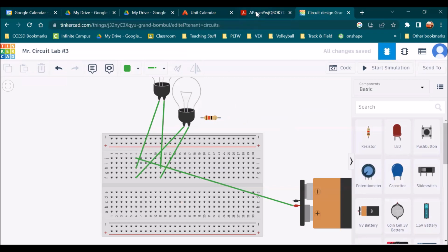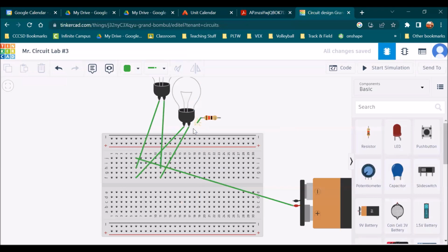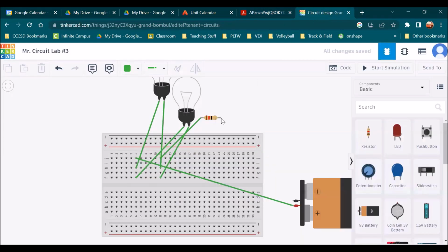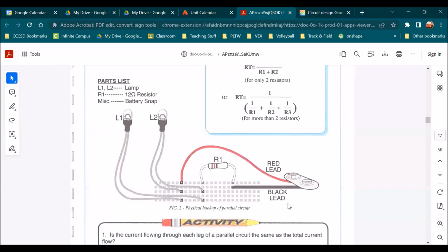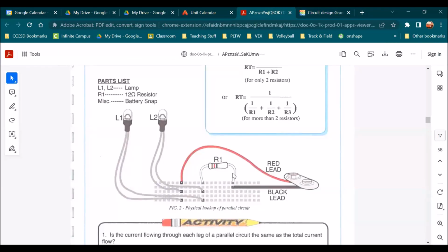And click on the left side of my resistor, and that goes into the same row that we just left off on with 2 lights. Like that. The right side of it is going to go, I think it's about 7 squares to the right. So we will go here, 1, 2, 3, 4, 5, 6, 7. Okay. And then last but not least, we need to connect this black lead wire from our battery, and that will form the loop. Now that goes in the same row that we just placed the resistor in.